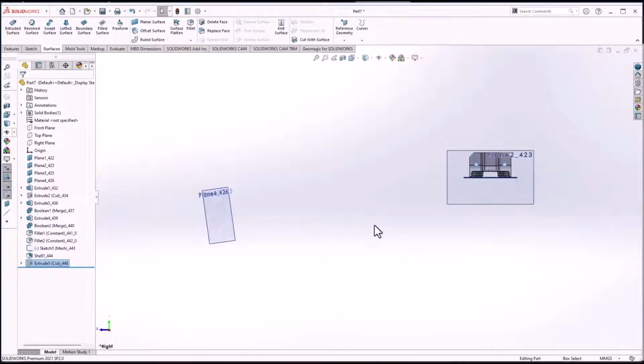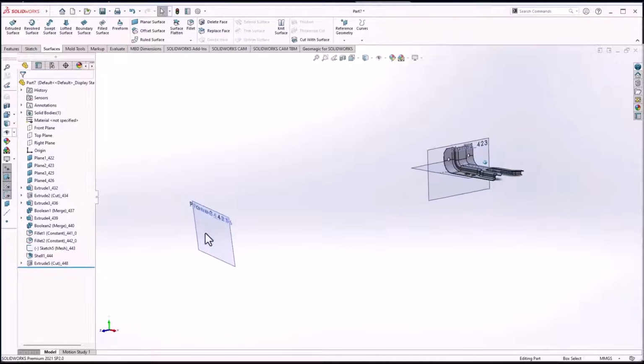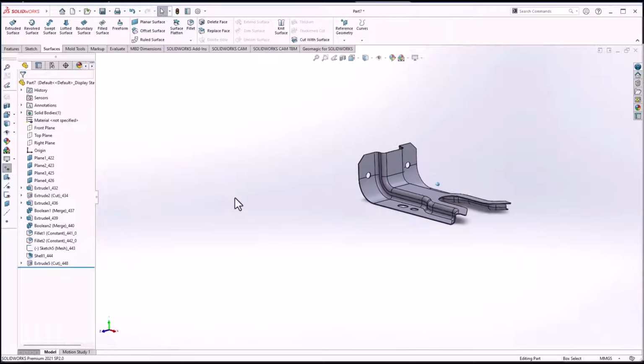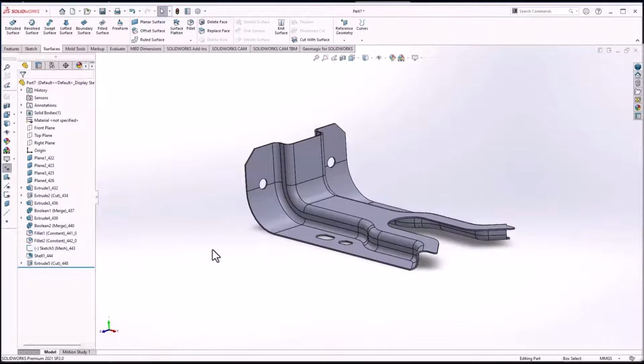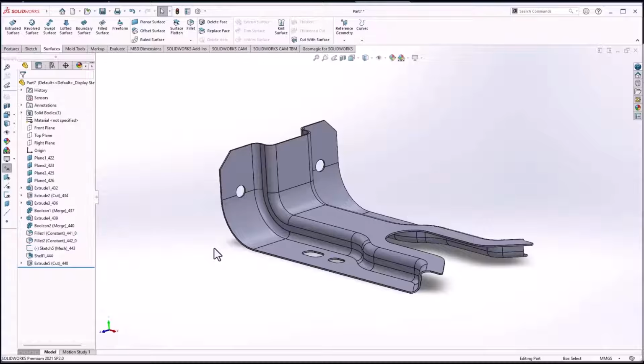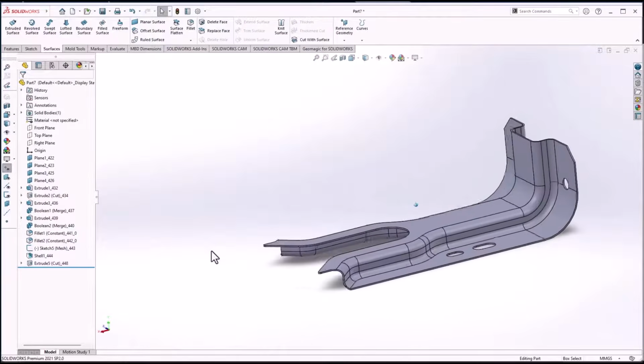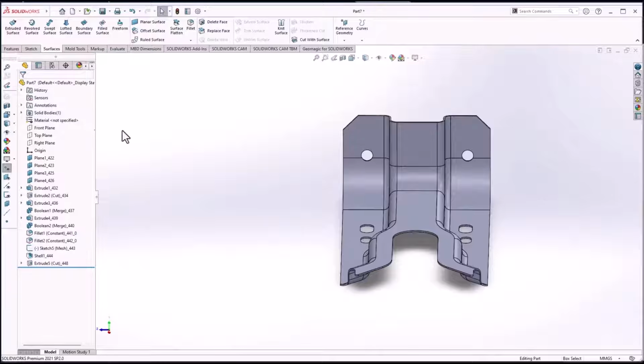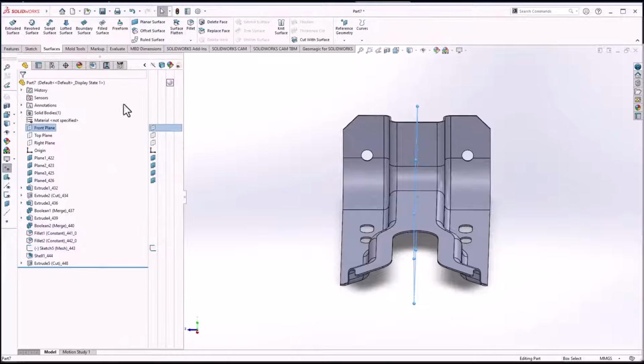Now, you'll see here that it leaves some stuff showing. So if I'm going to do live transfer from Design X into a CAD, I keep these little view filters handy where it'll say hide all planes, hide all sketches, hide all axes, that sort of thing. Because when it transfers over, I don't think it's Design X, I think the CAD package has everything showing, right? So there, we just sent this over as native entities inside of SOLIDWORKS. And then if I just extend this out, I like to do it this way.